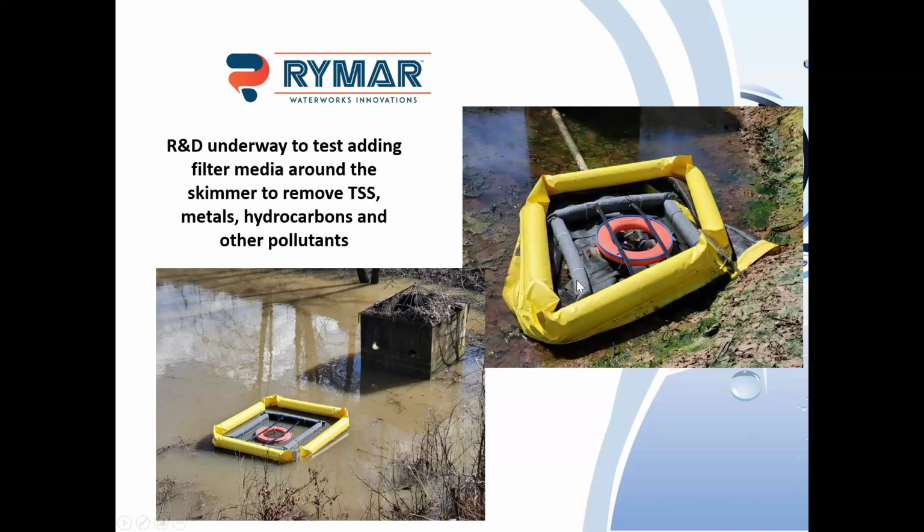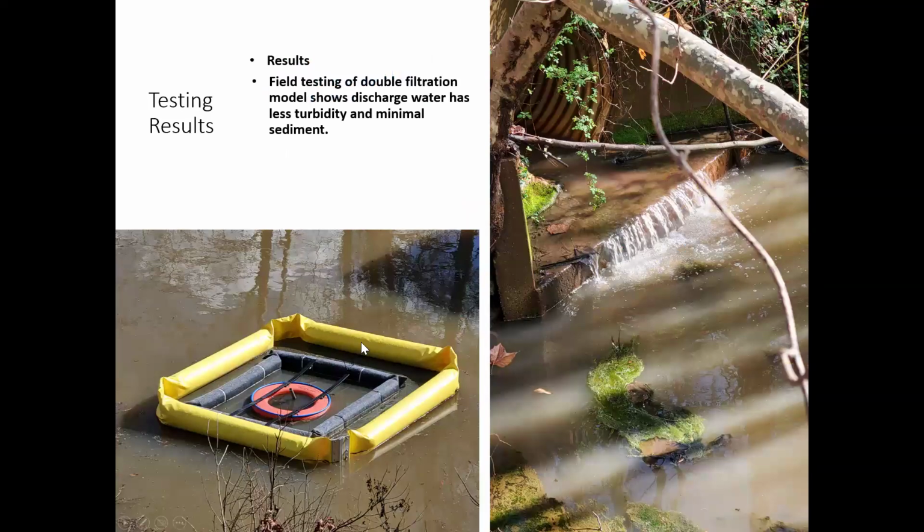And then the inner one, what we ended up doing is actually have 2 layers of fabric. We put basically 6-inch slits or panels there, and we offset the panels 3 inches so water kind of weaves through that fabric, creates more contact with this material. Somewhat sticky, it kind of grabs the sediment particles and other polluted particles as they come through there with the contact time.